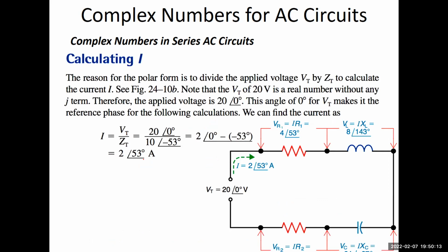And this is how you calculate I. Again, to calculate I, you just follow Ohm's law. So the total current would be equal to the total voltage divided by the total impedance Z. Di ba sa DC analysis sa Circuits 1 natin ganun din? I is equal to V over R. Yung Z sub T, yun din yung R because Z sub T is measured in ohms. R is measured also in ohms. So we could make use of Ohm's law.